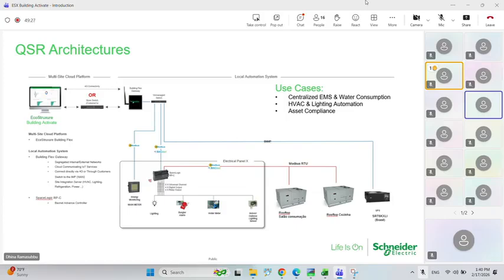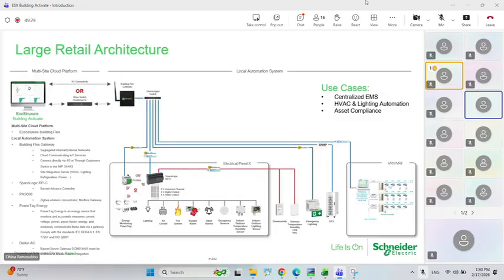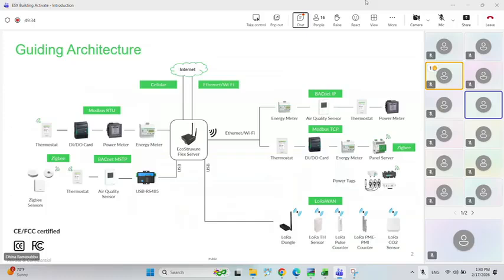So Dina, can you go to the previous slide with all the protocols? Yes, this one. For example, for the BACnet MSTP and the Modbus RTU, we are limited by the number of ports. But for the things communicating on Ethernet or Wi-Fi, is there any limit to the number of devices? Since it's one Ethernet port connected to the network, can we do as many BACnet IP or Modbus devices as long as it's less than 50 devices?